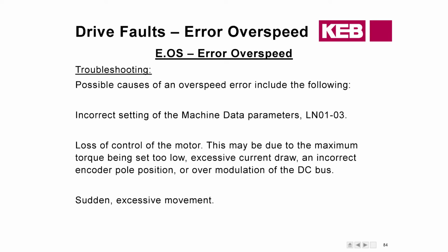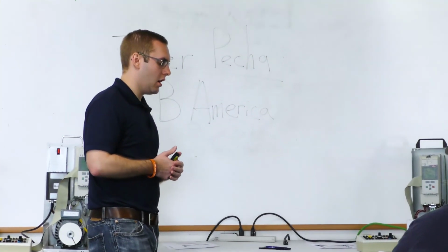So run the car on inspection, look at your motor speed and your command speed. They should match. If there is a difference there, then that likely indicates you have a scaling problem. A few other notes on this.